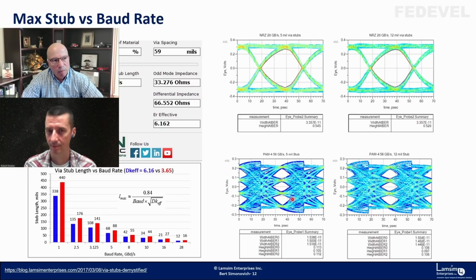And so people have different ways of achieving that rate. But the PCBs are kind of running out for long lengths at the higher rates. It's getting more challenging. That's why you're finding what they call flyover cables, coaxial cables as jumpers to spread the gap at the higher rates.